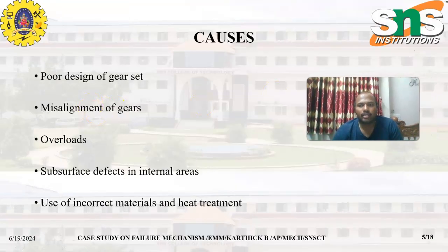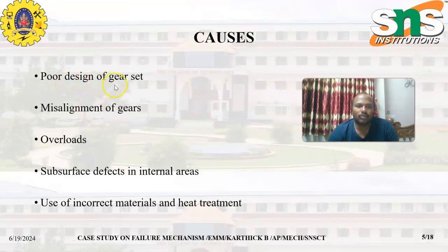So here the main causes are poor design of gear sets, misalignment of gears, overloads, subsurface defects in the internal areas, and the last one is usage of incorrect material and heat treatment.